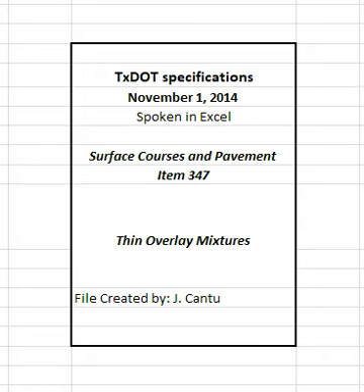4.8 Compaction. Roll the freshly placed mixture with a steel-wheeled roller without excessive breakage of the aggregate to provide a smooth surface and uniform texture. Operate the roller in static mode for TOM-F mixtures only. Do not use pneumatic tire rollers. Use the control strip method given in Tex 207F, Part 4, to establish the rolling pattern. Thoroughly moisten the roller drums with a soap and water solution to prevent adhesion. Use only water or an approved release agent on rollers, tamps, and other compaction equipment unless otherwise directed.